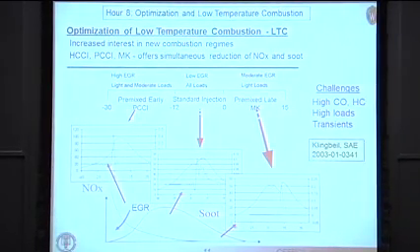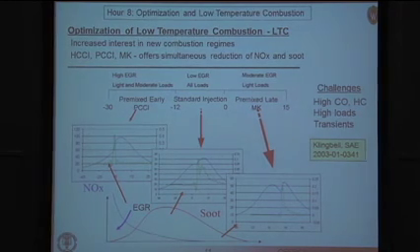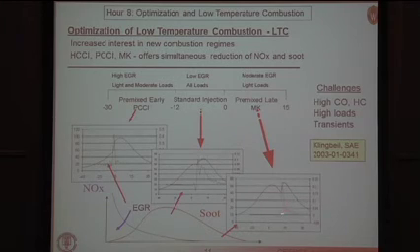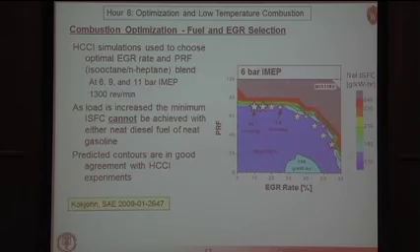that NOx down. And if we look at late combustion, so-called modified kinetics combustion, injecting after top dead center, you can get something that looks very similar to the early injection case here. And in fact, this has both low NOx and low soot. But combustion stability is an issue here, because if you miss the appropriate combustion timing, you can get no combustion at all if you inject too late. So a lot of challenges with operating engines in these low temperature combustion regimes.